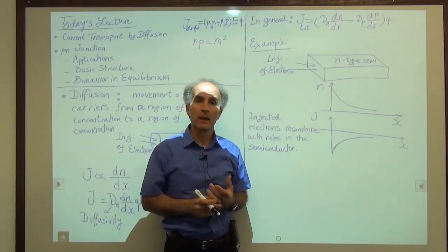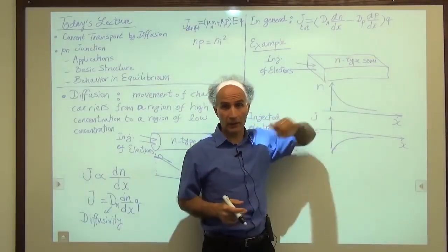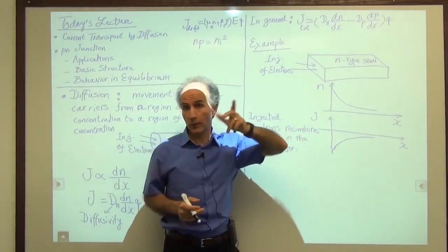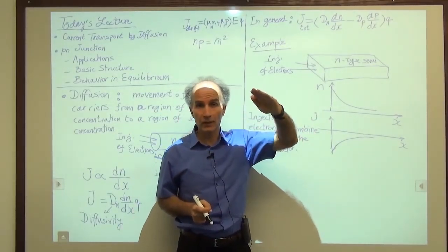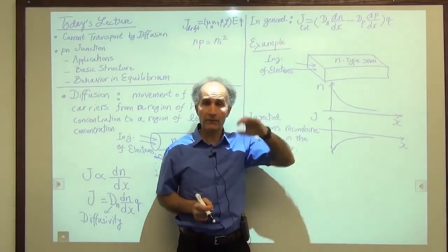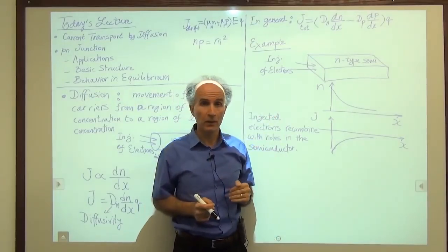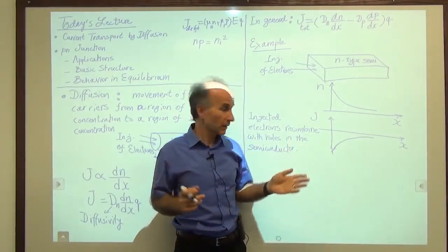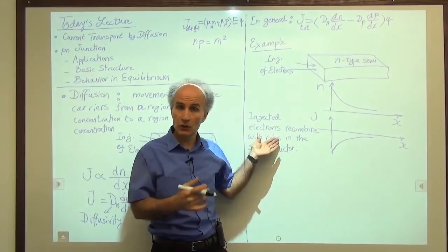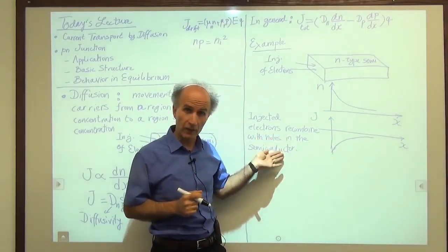Now you may say, well, I doped this semiconductor with a donor, let's say phosphorus, so much that the number of holes available is very, very small, orders of magnitude smaller. So this shouldn't happen because we just don't have enough holes for recombination.